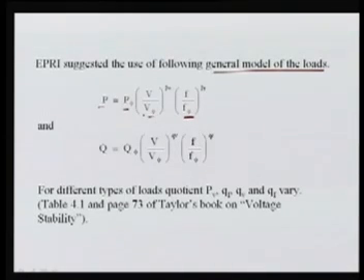So if your system frequency is changing, then this P will also change. So this is now a general-purpose model. Here there are the exponents: there is the PV, and here it is PR. Similarly, here we have the QV and the QR. So PR is the exponent of this term, and here PV is the exponent of V, the actual voltage divided by the rated voltage. Now these coefficients are exponents here, PV and PR.